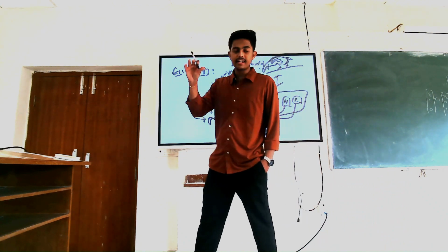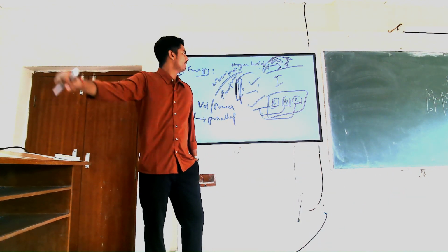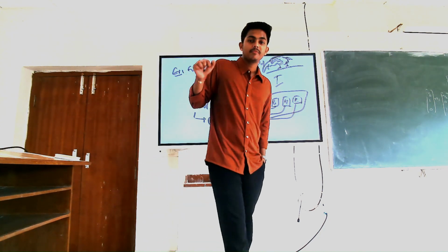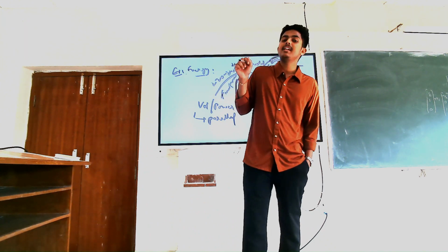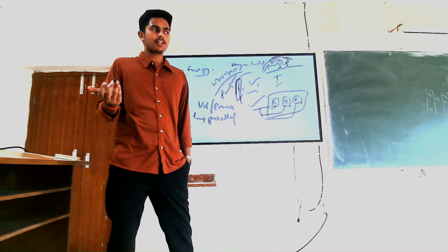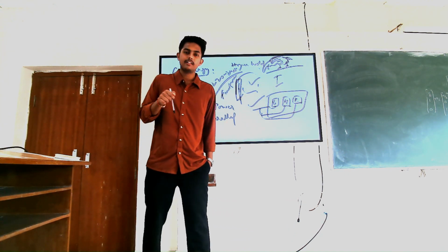In general, if we catch any wire or conductor which has electrons flowing in it, we get a shock, right? Why is this not happening? We get a shock only when one terminal is caught and the other terminal is at some other potential or voltage. If we are standing on the ground, it's neutral, a zero potential.